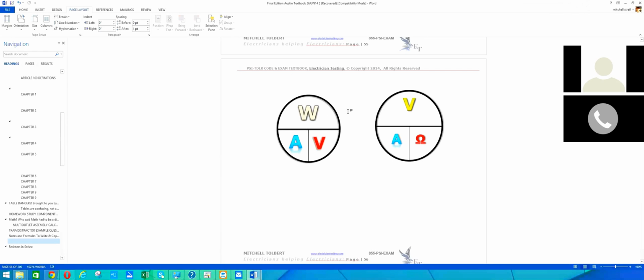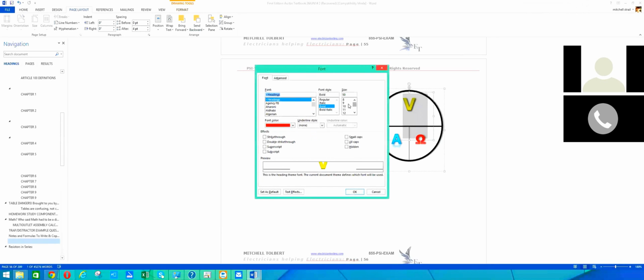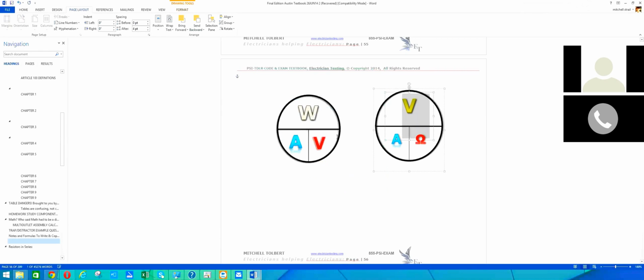Just a quick note, all your watts and volt amps and power, true power and apparent power, it's 100% unity. So there's not any power factor losses or efficiency losses. You can interchange a watt and a VA just fine without worrying about there being any kind of losses there. All right, so that's that part. Let me make this a little bit bigger so it'll be easier to see, and move down there.